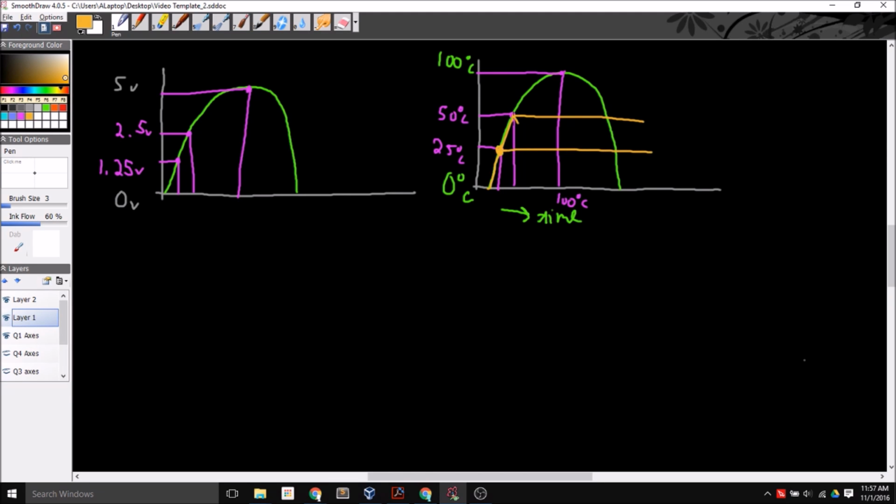So I could turn on the heater and then turn off the heater over and over again, so it's not quite boiling and it's not quite cooling down all the way. It's just getting a nice warm temperature. Maybe this is a little coffee pot or coffee cup warmer. So basically I can constrain my output to turn on and turn off my heater element based on this analog input that I'm reading.